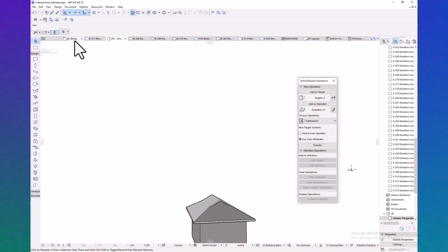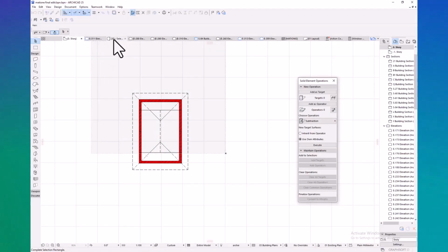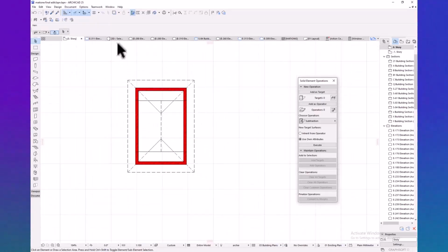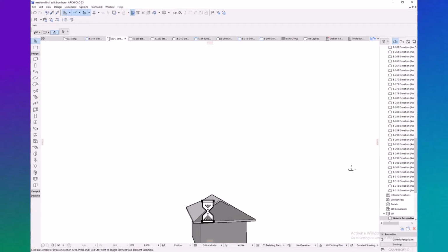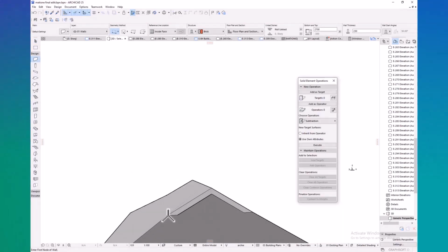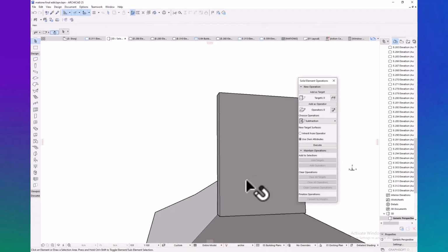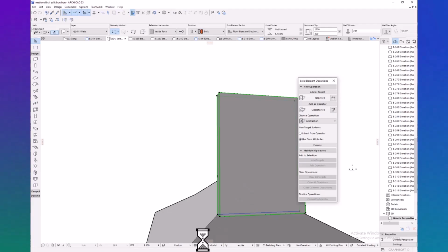Now we're going to need to cover up those openings on the Dutch gable, so we have to add our wall. Activate our wall tool. Right. So back in 3D, go to design, activate our wall tool. And we come in here, we click this corner, there's our wall, all the way until the other side. Okay, as you can see, the wall is inside the gable, so press Ctrl D and move it around. And there we go.